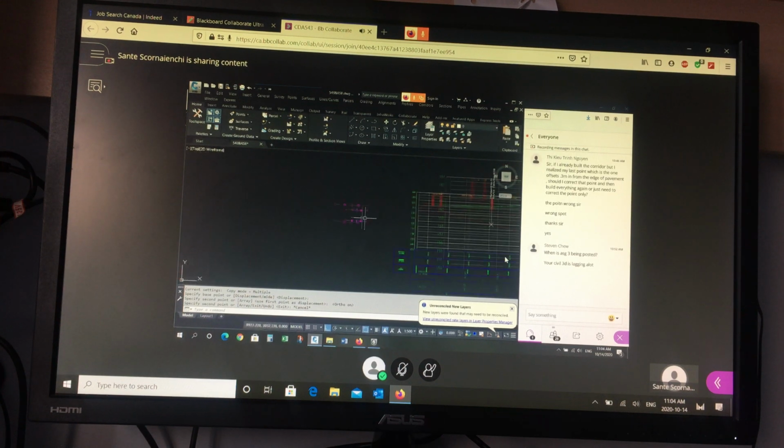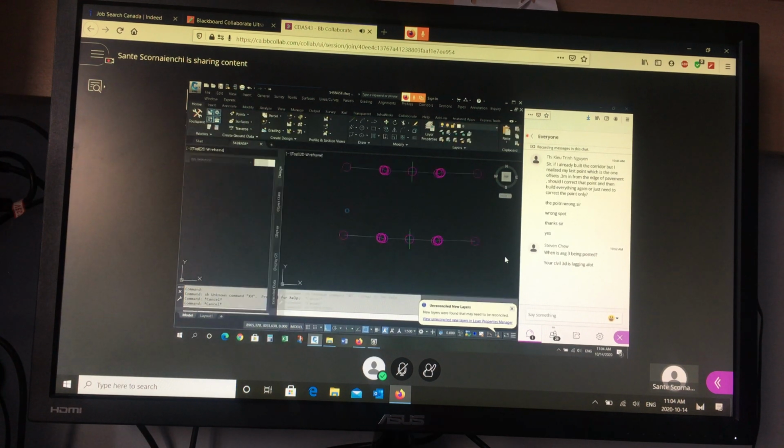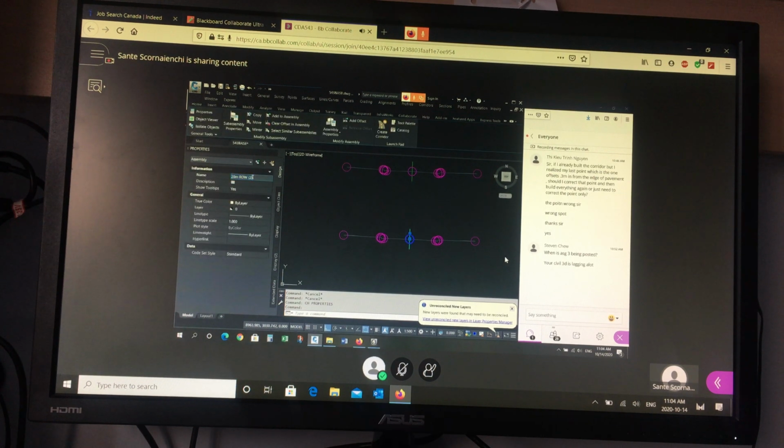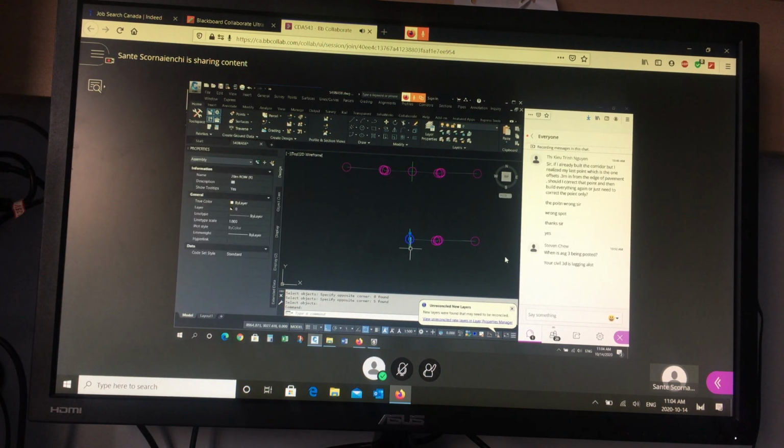So I'm going to change the name just so I can find it. It actually indexes it when you make a copy, so it's going to be called right-of-way 1, I believe, or right-of-way 2. I don't want right-of-way 2. I'm going to say 20-meter right-of-way, and I'm just going to say R for the right side only. And then I'm going to modify it. This side is not representative. But on the inside, this is correct. So you go along your standard 20, and when you go around the curve, the inside is exactly the same as before. The outside is wrong, so I deleted it.